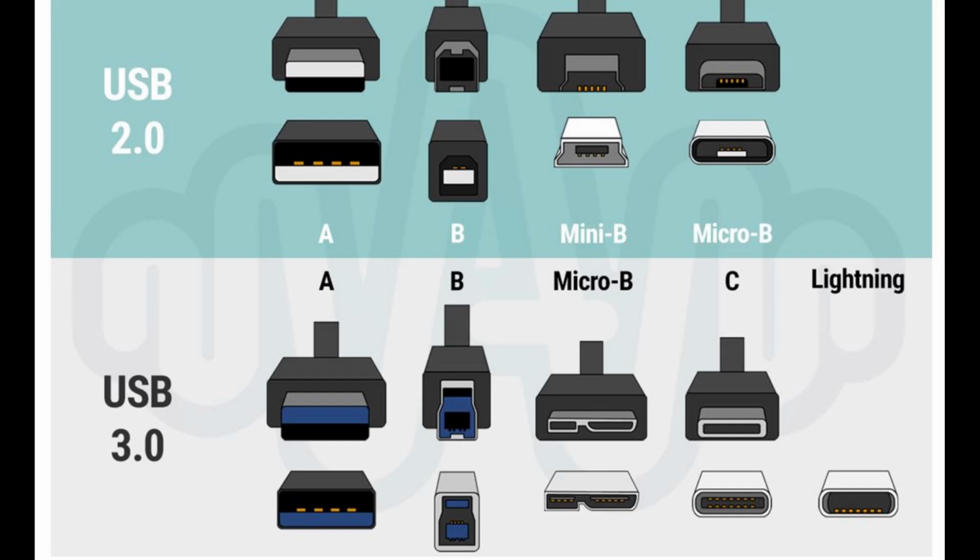While converters exist between certain legacy interfaces and USB, they might not provide a full implementation of the legacy hardware. For example, a USB to parallel port converter might work well with a printer, but not with a scanner that requires bidirectional use of the data pins.